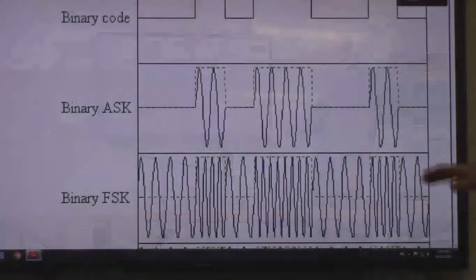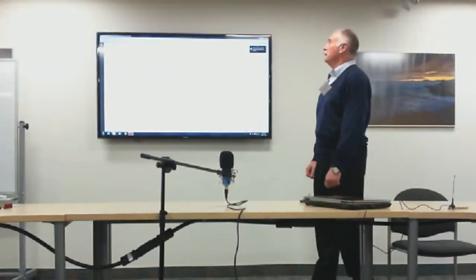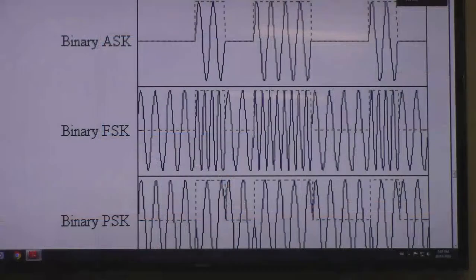A little up, please. Now we look at binary frequency shift keying coding. In frequency shift keying, both the zeros and the ones cause the radio to receive a tone. The tone could be a higher frequency and a lower frequency, such as 600 Hz and 1000 Hz, for instance. Both are audio frequency tones well within the range of the transmitter.